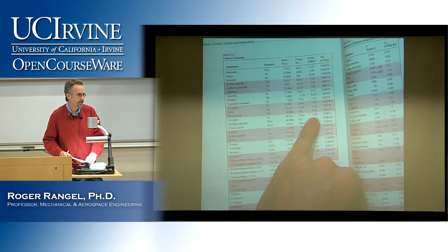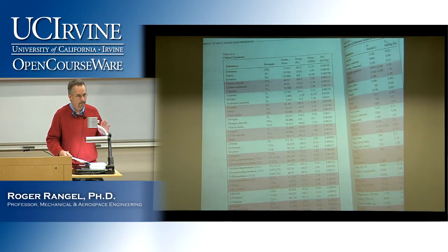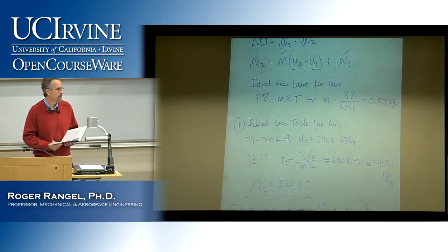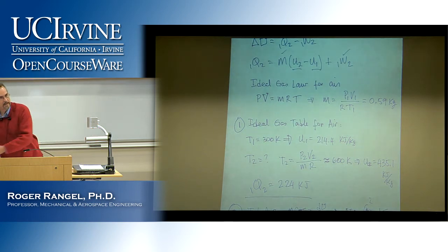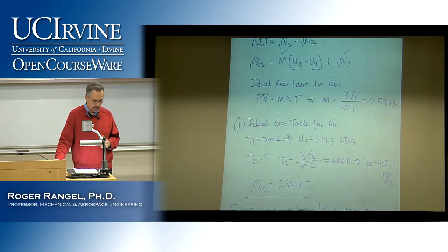And we are at 100 and some. So our pressure for our process is way below the critical pressure for nitrogen. And if you check oxygen, it'll be the same. So we are very safe. Unless the pressures are very high, you're safe using the ideal gas law.